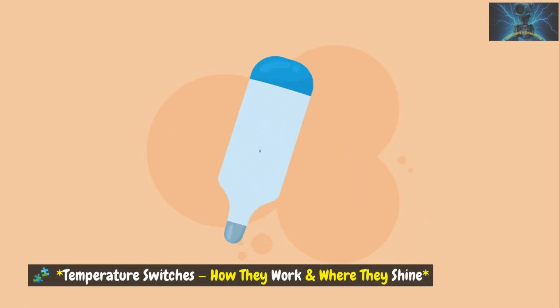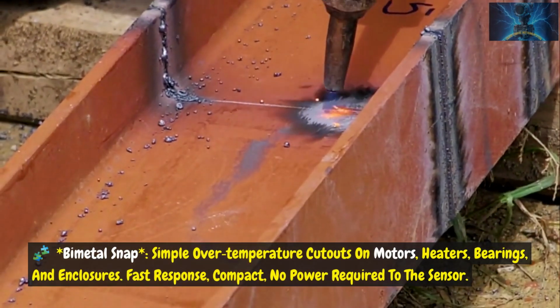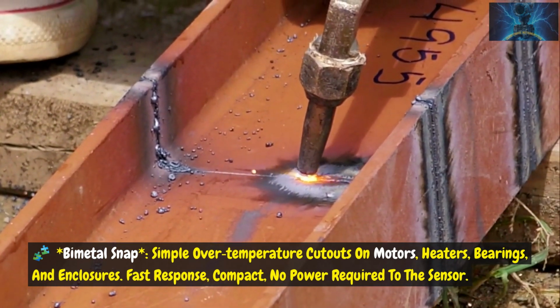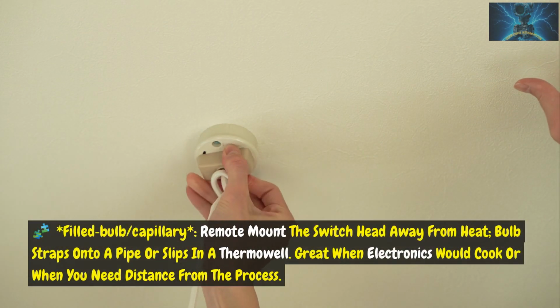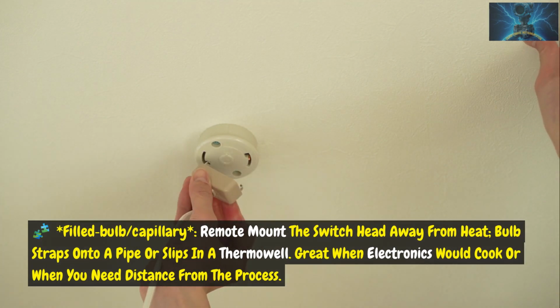Temperature switches: how they work and where they shine. Bimetal snap: simple over-temperature cutouts on motors, heaters, bearings, and enclosures. Fast response, compact, no power required to the sensor. Filled bulb capillary: remote mount the switch head away from heat. The bulb straps onto a pipe or slips in a thermowell. Great when electronics would cook or when you need distance from the process.